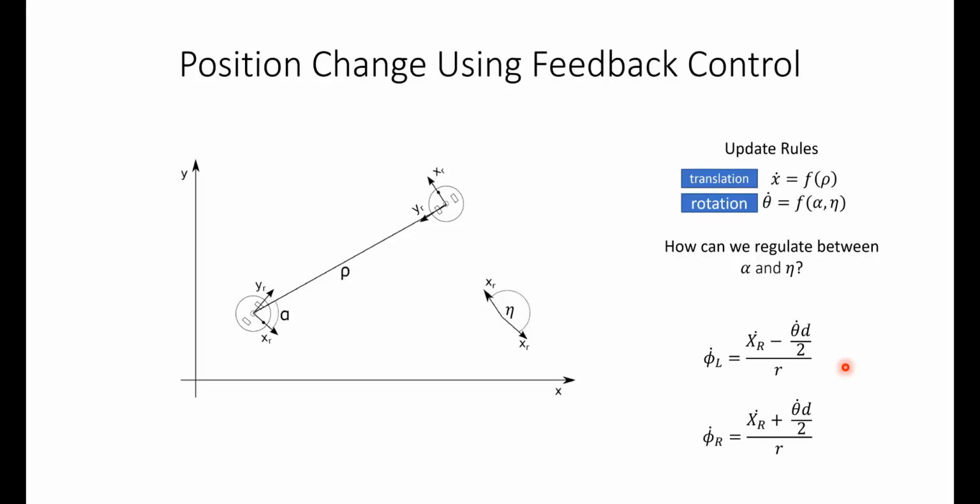And so if, for example, my right wheel needs to turn twice as fast as my left, or twice as far as my left, then I'll just set my right wheel to 100% and I'll set my left wheel to 50%. And so we're doing this mapping again from the total amount of rotations that need to happen to some kind of proportion. And that proportion is going to get multiplied into our max speed. And that's how we go through this system, right? So we have some sources of error and we eventually map that down to wheel speeds. And we're updating this constantly. And as we do that, we're never really going to get too far away from our goal. So we're always going to be converging towards our goal, which was the initial plan.